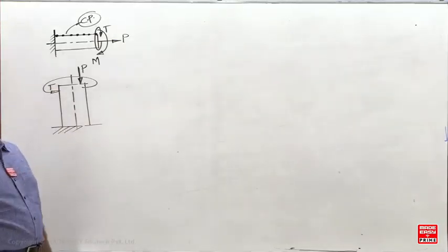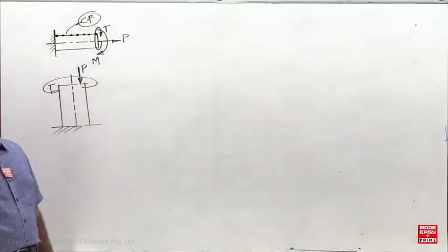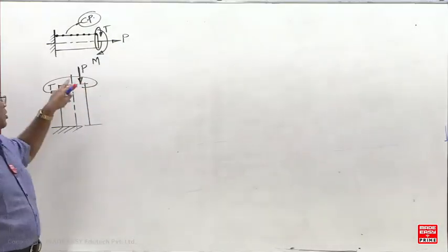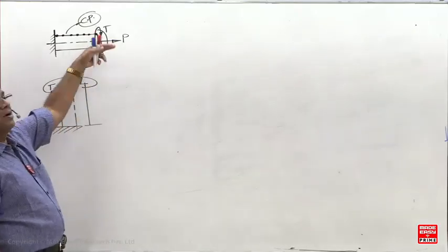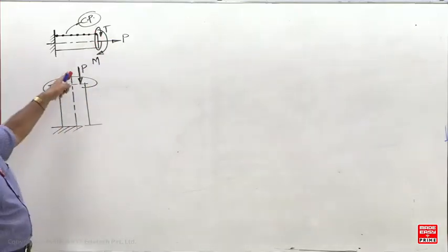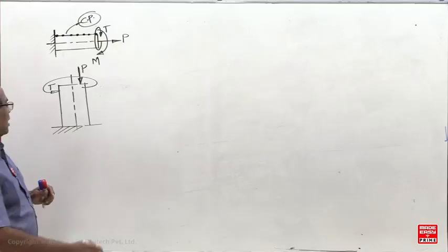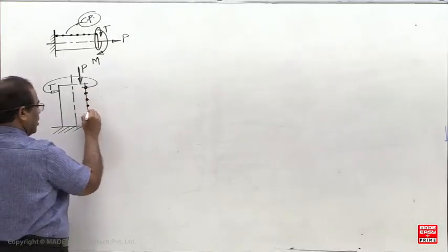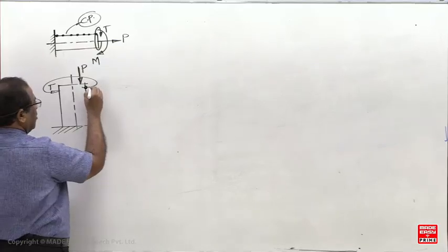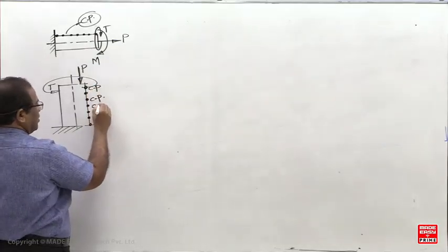Now which type of load is this? Eccentric axial compressive load. So whatever I have written there is equal to one compressive load, one bending moment and one twisting moment. Earlier it was one tensile load, one bending couple and one twisting moment, but here it is one compressive load, one bending moment and one twisting moment. So in this case, which one is the critical point? This is the critical point. Whatever I have written is valid at this critical point.